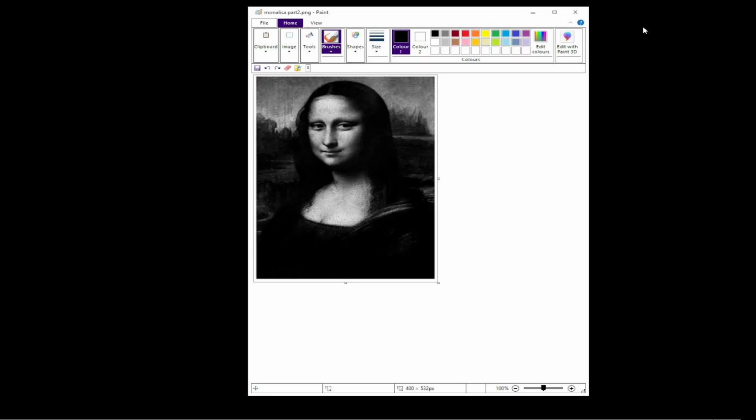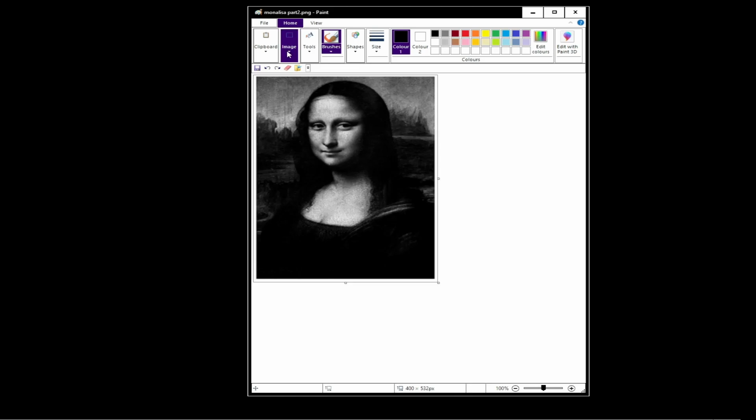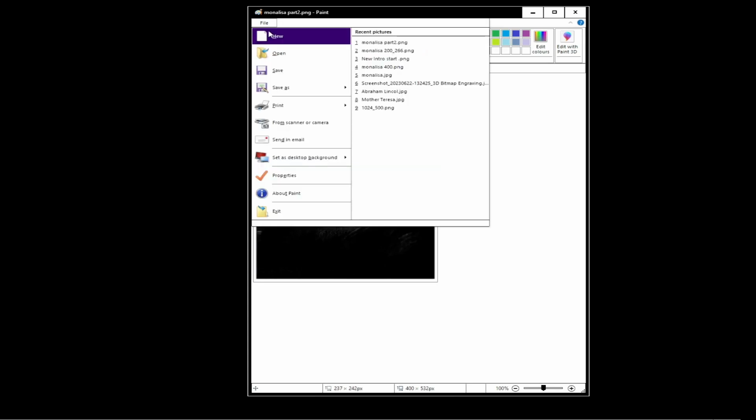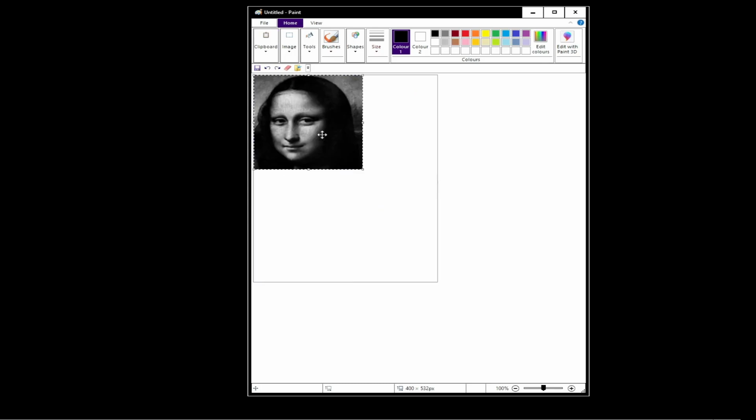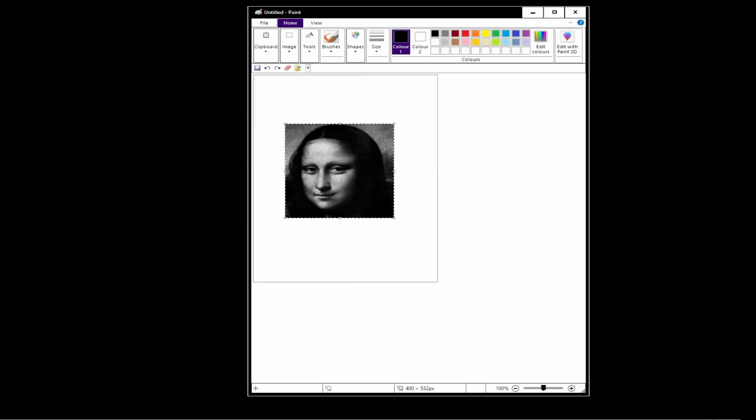Open the image in the Paint app and follow what I am doing. If you select the image to be engraved too large, your cycle time will be very long. Rather, scale your design with the width of engraving label in the app. Now you can save the image on your PC and exit the Paint app. Copy your image, like in tutorial part 1, onto your phone in the DCIM camera directory.